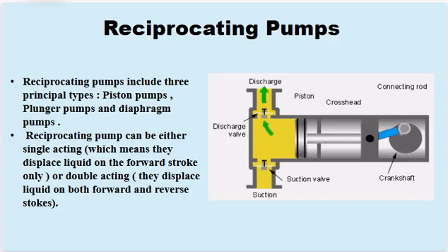Reciprocating pumps also come in two configurations. Single acting, these displace fluid on the forward stroke only. Double acting, these displace fluid on both the forward and reverse strokes, which provides a smoother, continuous flow. Thanks to their precise delivery and ability to handle high pressure or viscous fluids, reciprocating pumps are a go-to choice